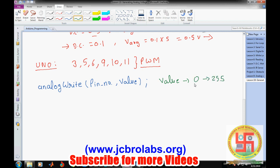For 0, T on is 0, and for 255, T on is equal to capital T. And these are the pin numbers. It could be 3, 5, 6, 9, 10 and 11, any pin which is supported by this Arduino UNO for PWM generation. So these two things need to be remembered.